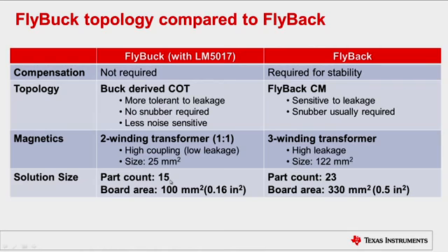As we can see here, for the similarly power design, the flybuck converter requires only 15 parts compared to 23 parts for a flyback solution, and the required board area is also much smaller.